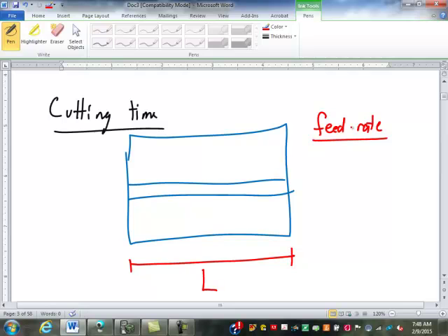Inches per revolution. Generally, it's like 4 thousandths or 3 thousandths of an inch per revolution. So we're going to call that F. That's our feed rate. And then we would need to know our RPMs, the number of revolutions. If it's turning faster, you're going to advance twice as fast than if you're only turning at 100 revolutions per minute.